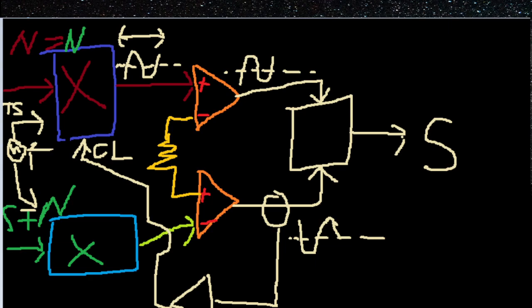And we set that up for a signal. We use a test signal to calibrate this. We set this up so we know for a fact that everything is perfectly in phase, even though it's 180 degrees out of phase, because if it's not in phase, then that's going to add noise. And the whole purpose of this is to try to get rid of the noise. This is my idea.